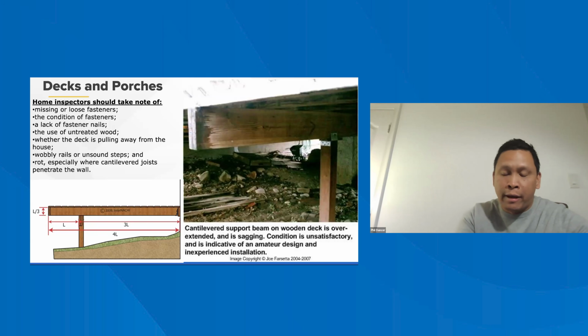The other important thing is, if you're standing on the deck, I know sometimes it's, oh, why are we doing it? But every once in a while, I actually come across it where I will stand in the center of the deck and I will try to rock myself back and forth with my feet. And every once in a while, I'll actually see the entire decking system rock back and forth with me. Not great. So very important to know that the deck is ready to use, or if it does need a little bit of care before we're ready to use it again.